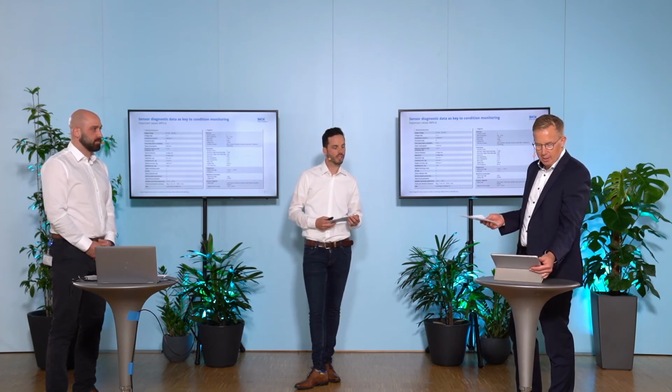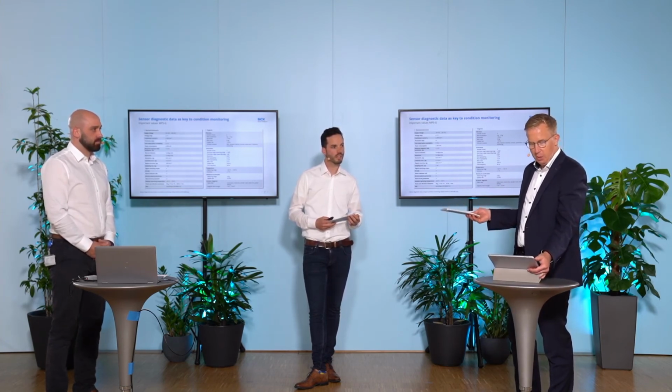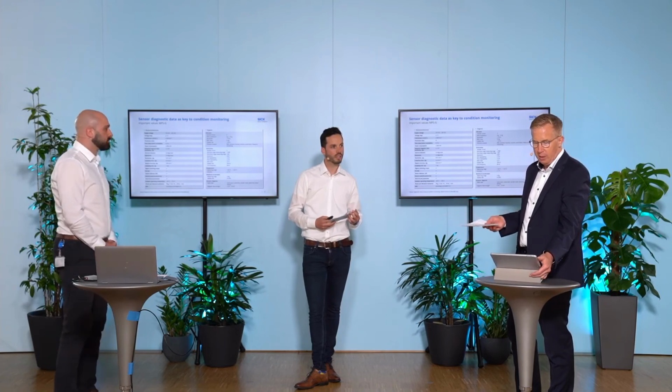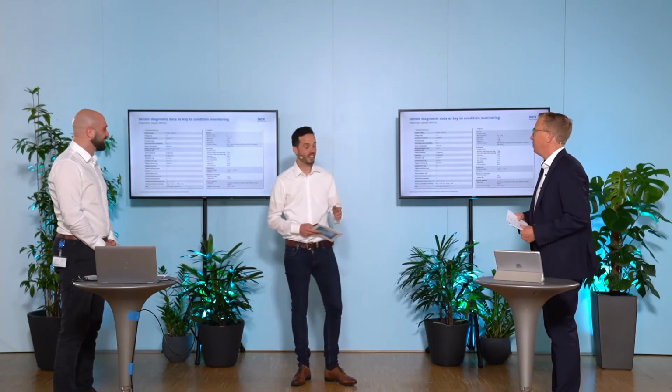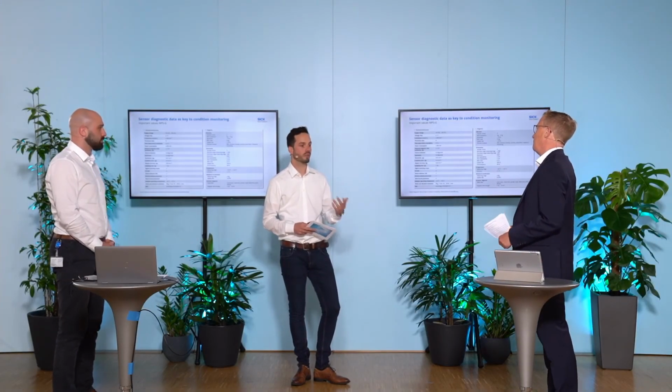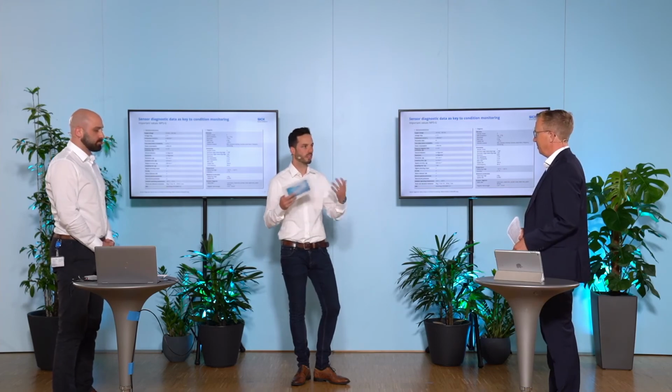There's another one. Are there more sensors equipped with diagnosis functionality? Say you're not super excited about cylinder switches, are there other sensors? It's also a very good question. Of course, we see the potential and also the trend for digitalization and added values out of one sensor. Up to now, we have a magnetic line guidance sensor, which is also equipped with vibration, shock detection, and orientation, which can be very useful for AGV guidance and all that stuff.